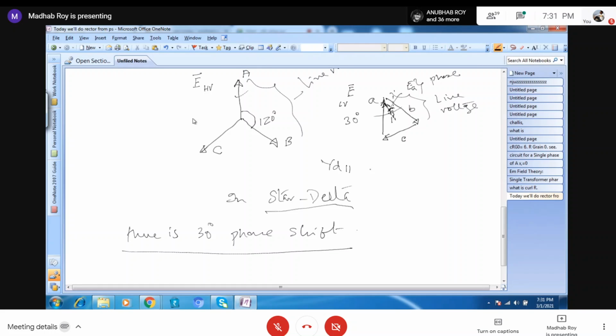In star delta it is a plus 30-degree connection. So when you do the YD11, that is called the plus 30 group. So that is a problem. When we do the star delta, then there is a phase shift. So this has become a very big problem when you do that, because you can understand, one transformer has finally come to, suppose, Mograhat. You know that Mograhat. It is a very big power grid.